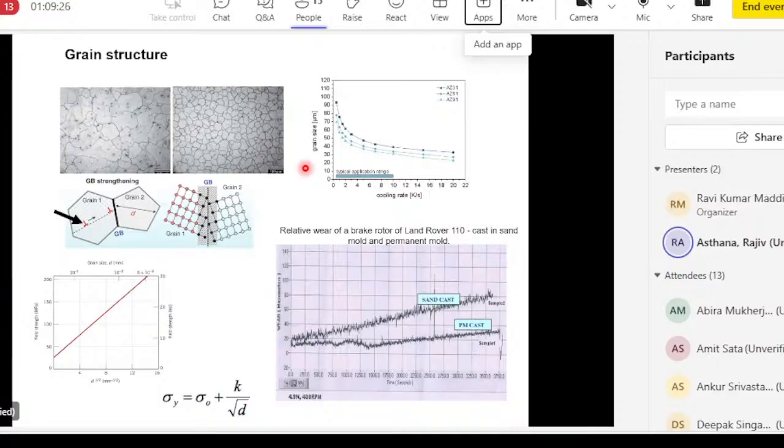In smaller castings, people use high frequency vibrations. As the liquid solidifies into solid, you apply an ultrasound, and that will mechanically break up or disintegrate grains. When sound waves propagate through a liquid, they create cavitation, which is basically formation and implosion of very fine gas bubbles. And that process of implosion creates huge accelerations locally, or huge forces, that can break up crystals. So that's a mechanical method of refining the grains.